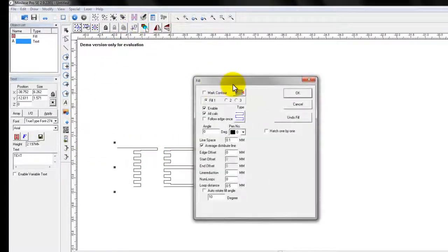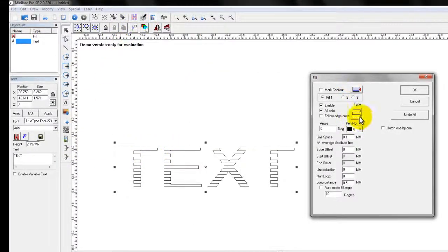This particular fill that we're showing you here, with the laser staying on as it turns the corner, will process each object one at a time, as opposed to turning off to jump between each object and switching back and forth as it jumps across the characters. It is going to mark the T, then the E, the X, and then the T again, and it will from time to time break these characters into pieces. This fill is used particularly to optimize your speed.